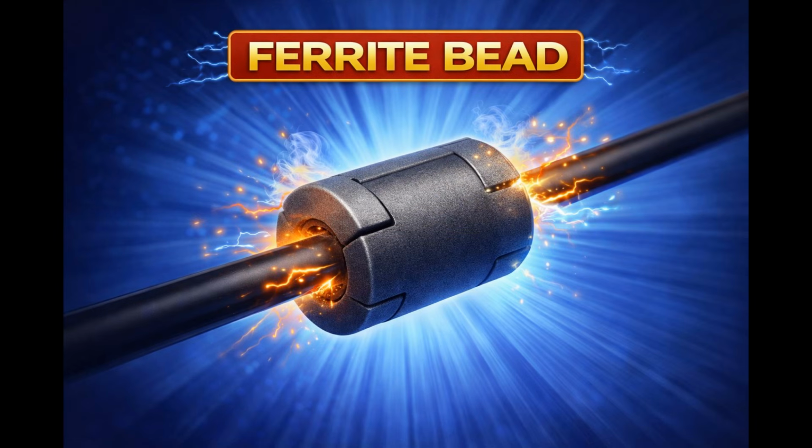A ferrite bead is a small but powerful tool used to control unwanted radio frequency energy. Made from a magnetic ceramic material called ferrite, it is placed around a wire or cable to suppress high-frequency noise while leaving the desired signal largely unaffected. At normal operating frequencies, such as DC, audio, or the intended RF signal, the ferrite bead has very little effect. However, when unwanted high-frequency noise or stray RF currents appear on the line, the ferrite bead presents a high impedance and absorbs that energy, converting it into a tiny amount of heat.